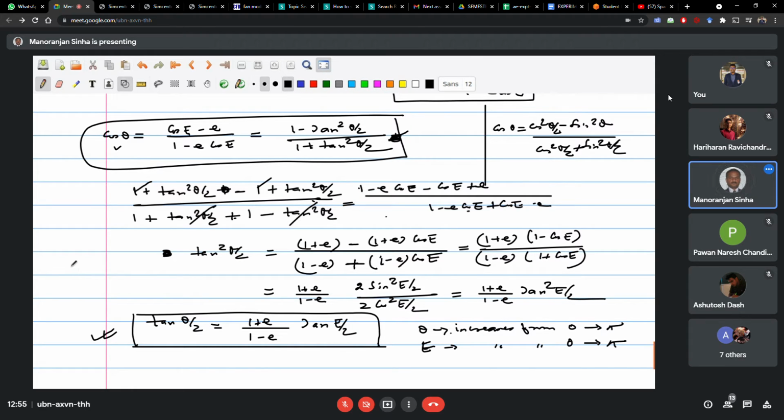What we have to do is propagate the orbit. This is our objective. So propagating the orbit, we take this equation r square theta dot equal to h and write this as d theta by dt equal to h by r square, or dt equal to r square divided by h d theta, and integrate it, where r is a function, r equal to L by 1 plus e cos theta. So integrating it is not as straightforward. For the parabola, you can integrate it directly, but for hyperbola and the ellipse, we need all this manipulation described here.